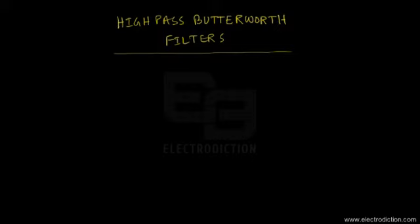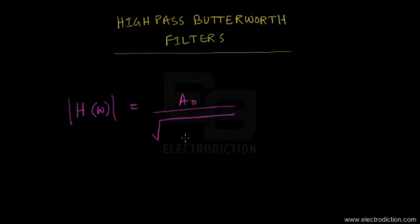Okay, so let me just tell you that whenever we talk about high-pass filters, the Butterworth filters especially are basically characterized by this sort of a transfer function. So that is H of omega, let's just take its mod value. That's going to be equal to a0 divided by root over, since it's a mod value of this thing, 1 plus (omega 0 by omega) whole to the power 2n.